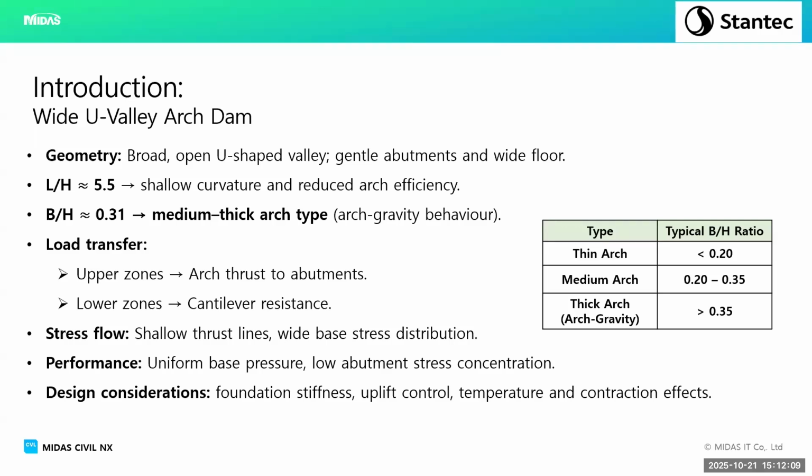and for this particular geometry, we'd expect approximately the upper two-thirds to have quite horizontal arching in terms of its principal compressive stresses, with the bottom third, 25% to a third, being cantilever in terms of tensions, vertical tensions on the upstream and vertical compressions on the downstream. So again, before we've set out any analyses, you've got this in your head of what to expect.